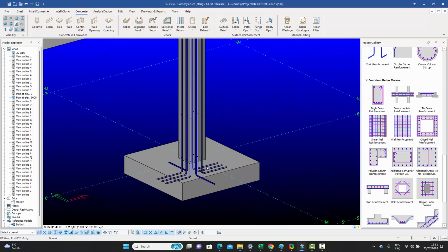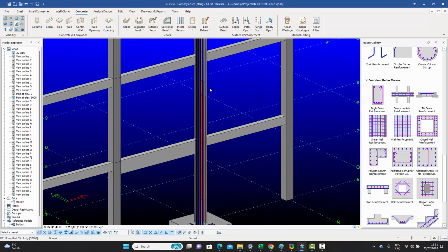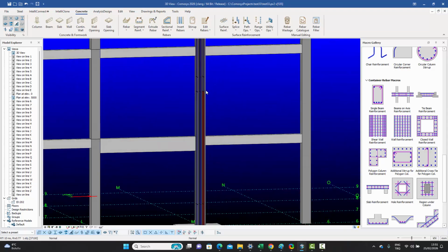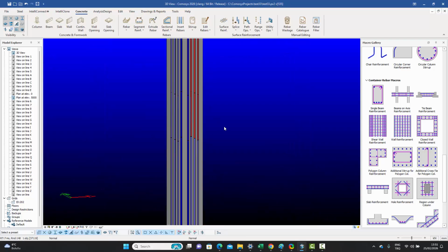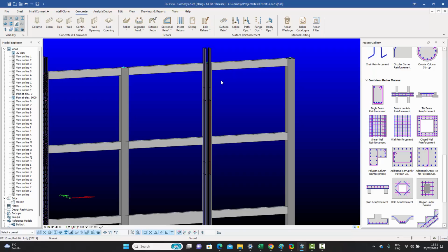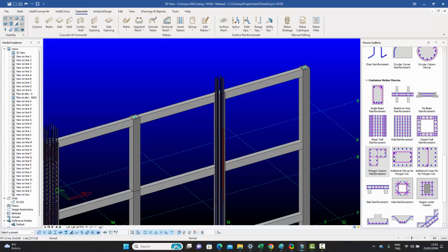And you will see that we've got the starter bars, and then we've got the first longitudinal bar. And the first longitudinal bar is getting a splice at 7,500 at that point. And then another longitudinal bar is continuing after that, and that one is getting a splice at 12,500, this level over here. And then the final bar is going out because my end condition was to cross the boundary. That's the default I have inside.